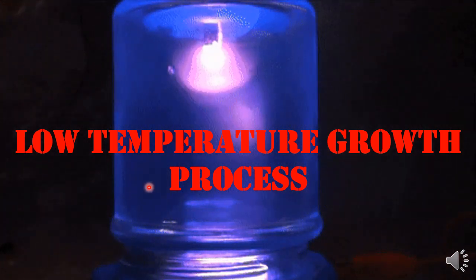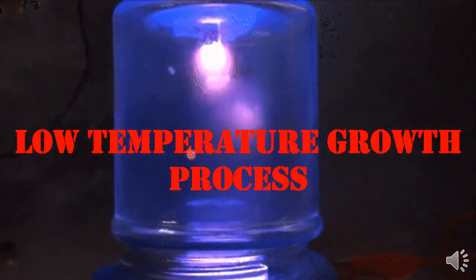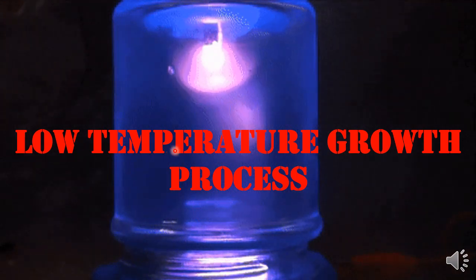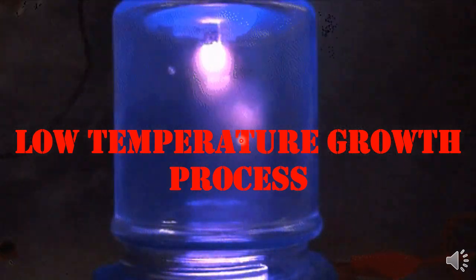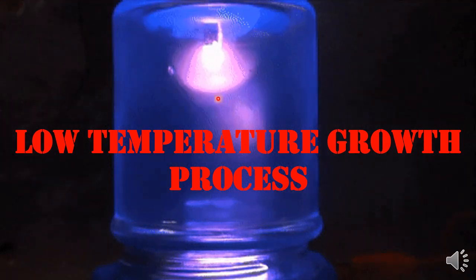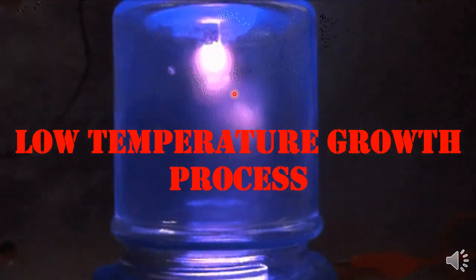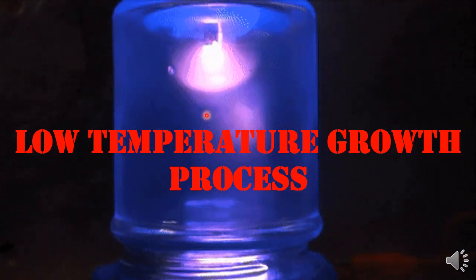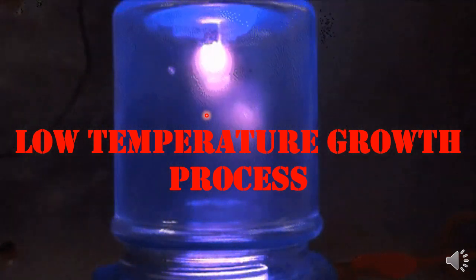Auto doping is the incorporation of impurity from the substrate into the epitaxial layer. Since the temperature is very low inside the reaction chamber, the possibility of impurity from the substrate to the epitaxial thin film is less, and due to this we can get a highly pure ultra thin film. So this technique allows the reduction of auto doping.